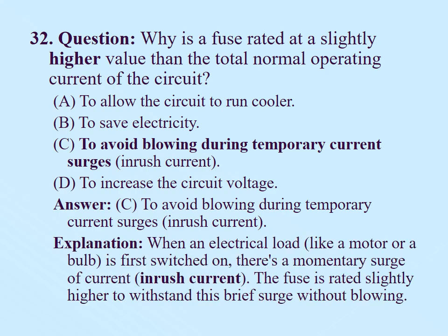When an electric load like a motor or a bulb is first switched on, there is a momentary surge of current. The fuse is rated slightly higher to withstand this brief surge without blowing. Next question.